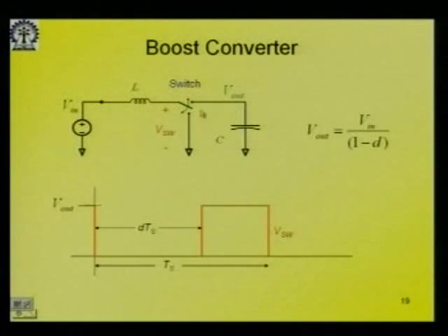While this switch is here, the capacitor voltage falls a little bit from the 2 volts to say 1.9 volt. And then once we put this switch back onto this, then this V in plus L di/dt, which happens because of the switching, will be greater than 2 volts and that will pump more energy back into the capacitor. So the capacitor will lose some charge during the on period, and then whatever charge is lost will be compensated.